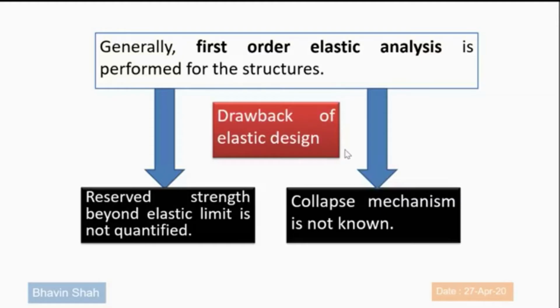Generally, for all structures, we are carrying out first order elastic analysis. And in my opinion, there are major drawbacks in the elastic design. First, the reserve strength beyond the elastic limit is not quantified. And second, the collapse mechanism is not known.